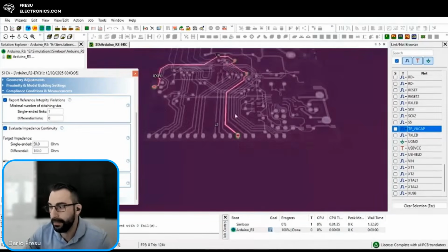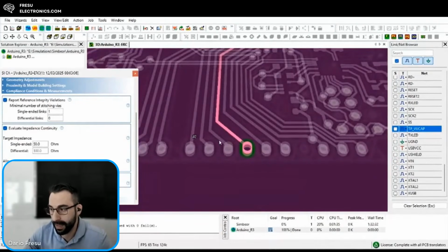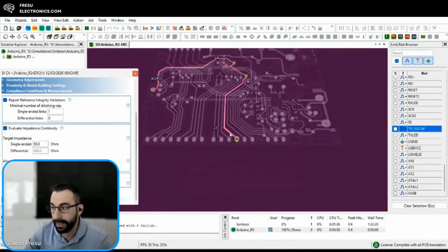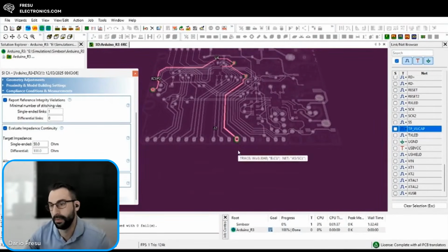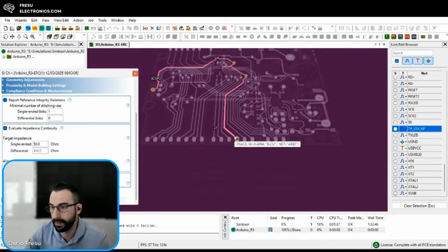So if I have just a little bit of signal coupling from this net to this net, I can already have common mode carriers that are trying to radiate out of the board because I have a cable connected in there. So this is also why it's important to have filters, not only for the input, but also for the output.